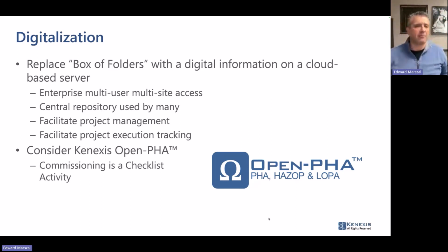There is one operating company that shall remain nameless that does everything on iPhones because even though an iPhone is not certified to be intrinsically safe, this operating company, and they're a big operating company, did their own testing to show that a certain model of iPhone in a certain case will not generate a spark that's capable of igniting a gas cloud. But that's just one operating company. Take that with a grain of salt. You can buy IS versions, definitely of like Android devices and Windows devices.